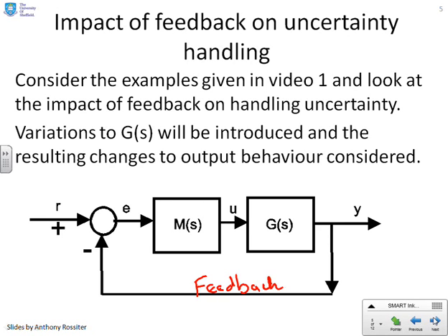Okay, so that's the monitoring. And then you've got what we call a summing junction, where that's actually a comparison between the target and the output. And then in here you've got a control law, okay, which says, given the information I've got about the error, what do I need to do to choose the input? And obviously this G represents the process.